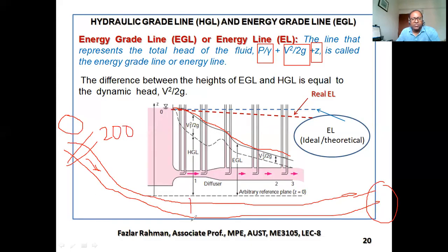So all the way right over here has to be 200, over here 200, over here 200. So if this point has a flow of water, obviously there will be flow as per Bernoulli's equation. If this is true, then one pump will be enough to supply crude oil from Iran to China by pipeline. But it is not possible because Bernoulli, he didn't add the frictional loss in the pipe.